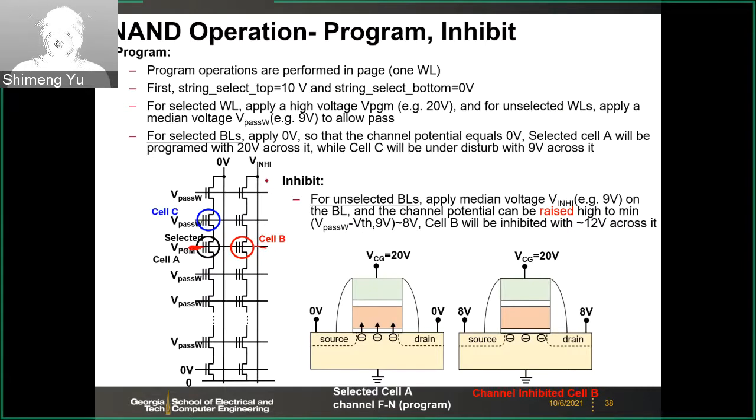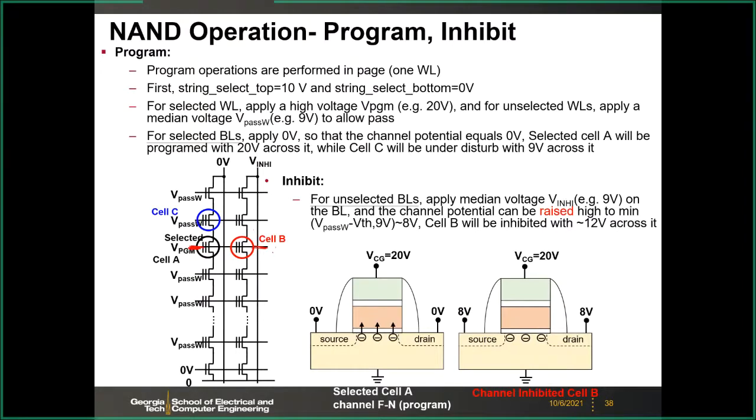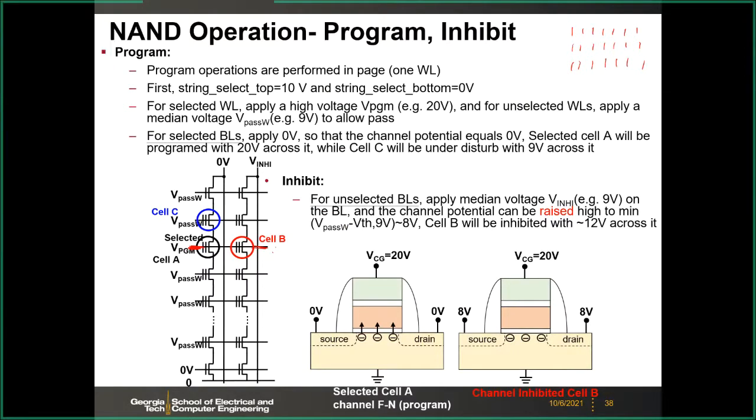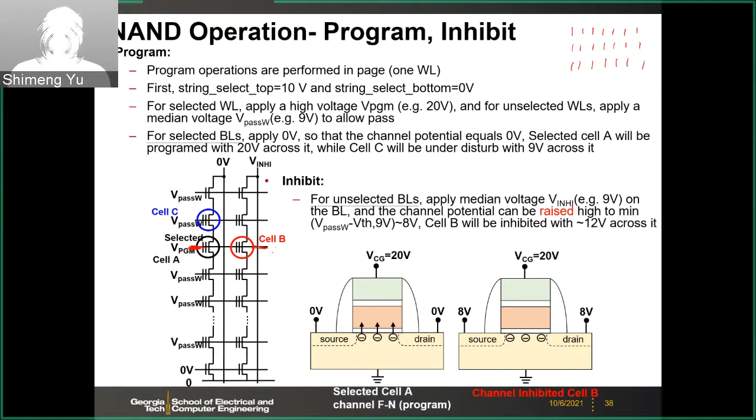So this is a selected word line. And you can select also certain bit lines to program. So think about it. The array, the block, after, because you do the erase by block. So that means after erase, all the data will be 1. Right? If this is the NAND flash block, that means all the data will be 1. This is like your initial pattern of the memory array.